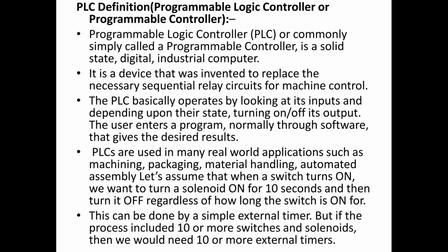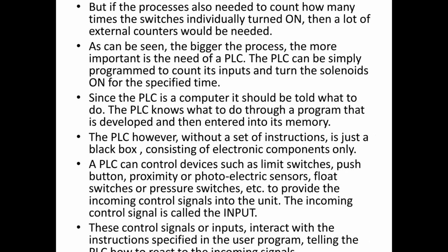So this can be done using an external timer. But if this process included 10 more switches and solenoids, okay, so many switches and many solenoids, then we need 10 more external timers. But if the process also needed to count how many times the switches individually turn on, then a lot of external counters would be needed. So this is going to become a bigger process, and so this can be replaced by the need of a PLC.